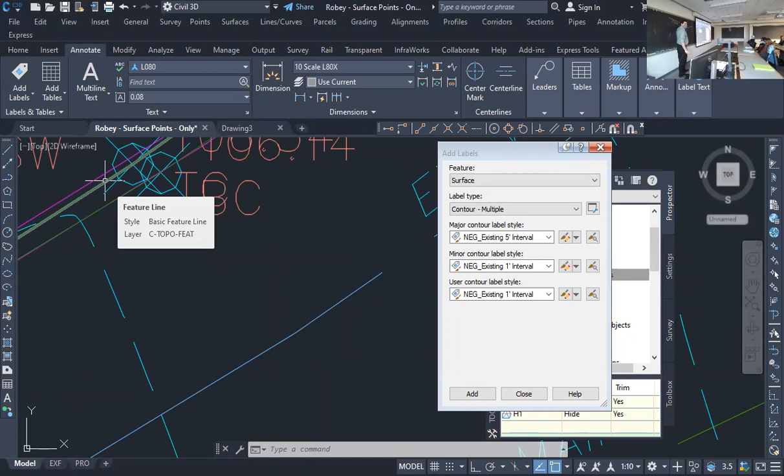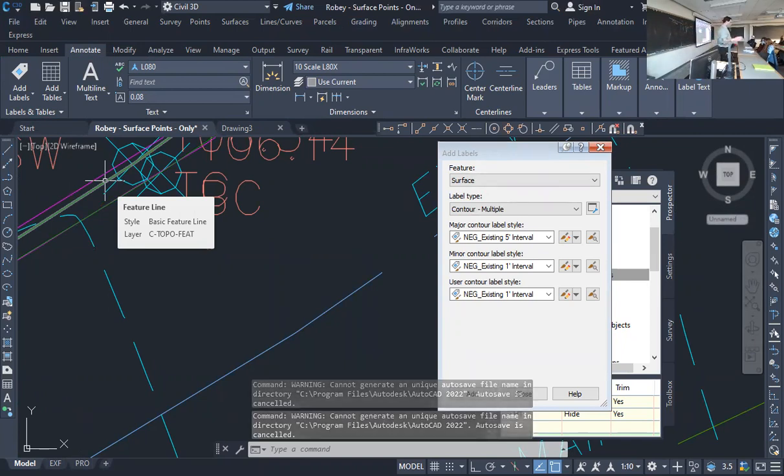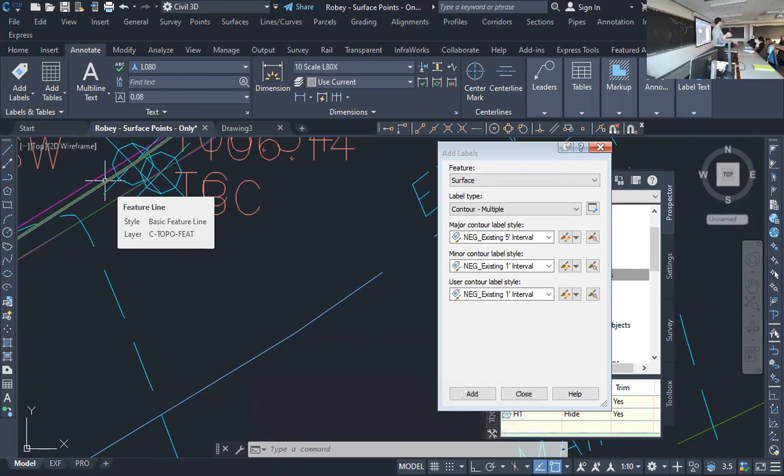The reason I do this is because usually this distance is only about 2 inches, 1 inch. And if you have two 3-dimensional feature lines in CAD and they cross, it's like Ghostbusters, you never cross the streams, it's bad, Egon, right? It gets confused. If you take a vertical surface this way and a vertical surface this way, we know that's probably a bridge or a tunnel or something. CAD's like, what are you talking about? So you want some separation between the two so they don't cross.